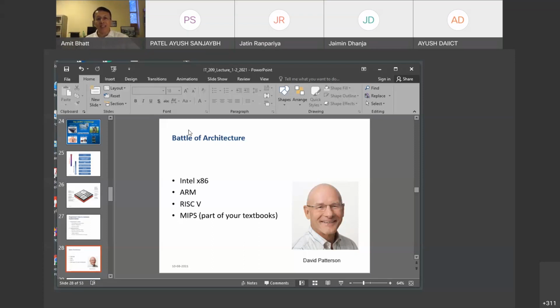So again, now come back to the word: what is an architecture? Architecture is something which you will call a spec sheet, or the things that a particular processor has to do to be called as having that particular type of architecture. So it is like, let's say, 4G or 5G. 4G or 5G is not a device. 4G or 5G is a standard. So it has a list of specifications. If your communication device meets those standards, then you can say that this is a 5G device. But 5G by itself is just a set of specifications. So Intel x86 architecture or ARM architecture is nothing but a set of specifications. It's an abstract concept. If you create an electronic product which meets those specifications, then you say that, okay, this processor is ARM architecture compliant or Intel x86 architecture compliant.